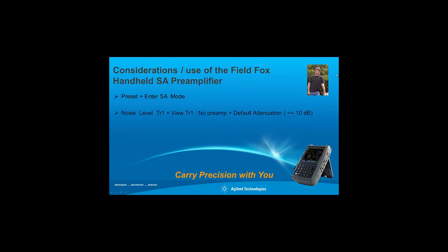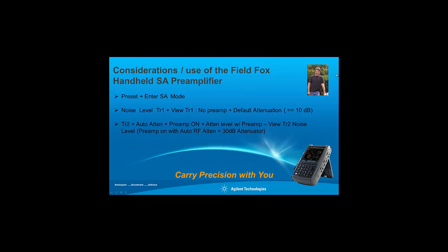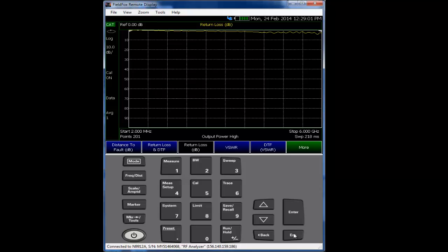I'm going to take a quick look at an opportunity in the operation of the FieldFox in the spectrum analyzer mode and use with the preamp. So the first thing we'll do here is perform a preset on the FieldFox. We'll then enter into the spectrum analyzer mode.